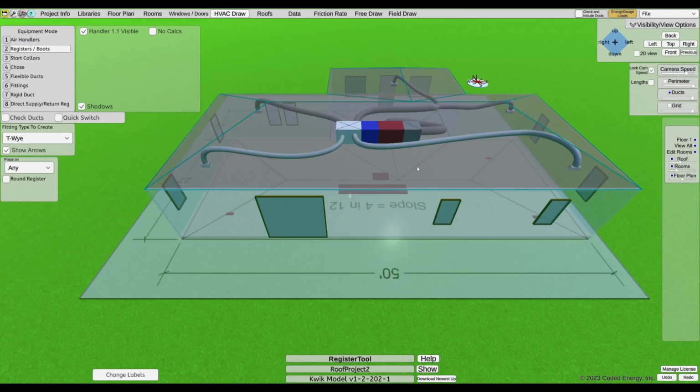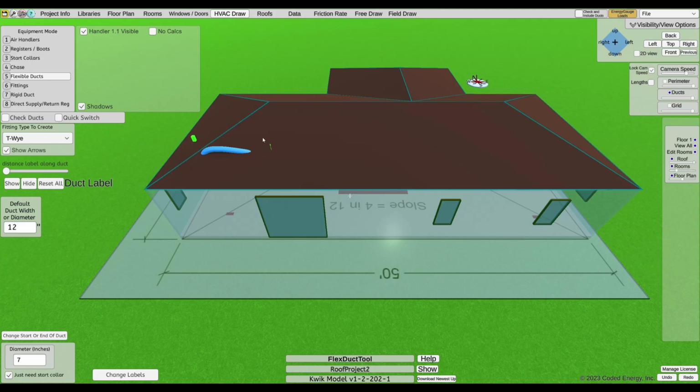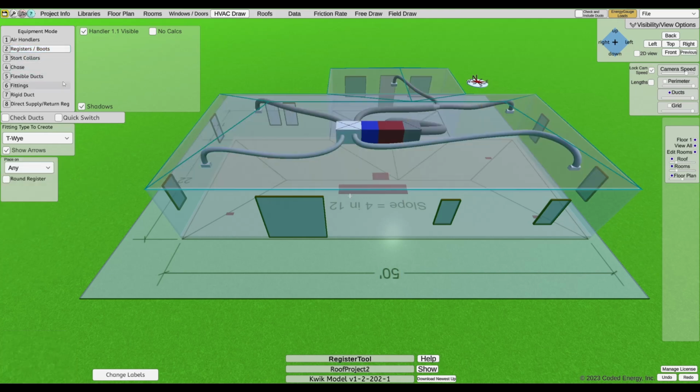When I was editing this video, I realized I forgot to show off one useful tip for when you're adjusting your ducts, and that's with the 90-degree and end registers. For instance, I had this one duct poking out a bit from the roof, as you can see. And instead of resizing the duct, which can be a bit of a pain, you can select the registers, click on the register, and it goes to the bottom left in this drop down, and we have the options for 90-degree and end registers.